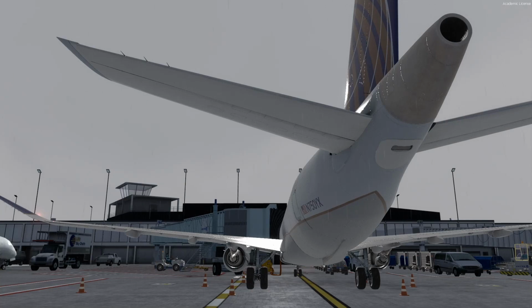On takeoff and climb, as the bleed air is taken from the engine compressor, this air is not used to generate thrust. Therefore, the takeoff and climb performance will take a hit. For takeoff, it means longer required runway, or to put it in terms we actually use, for a given departure runway and present conditions at the airport, like we are right now in Chicago, in certain temperature and wet runway and wind, etc. So that's a given.